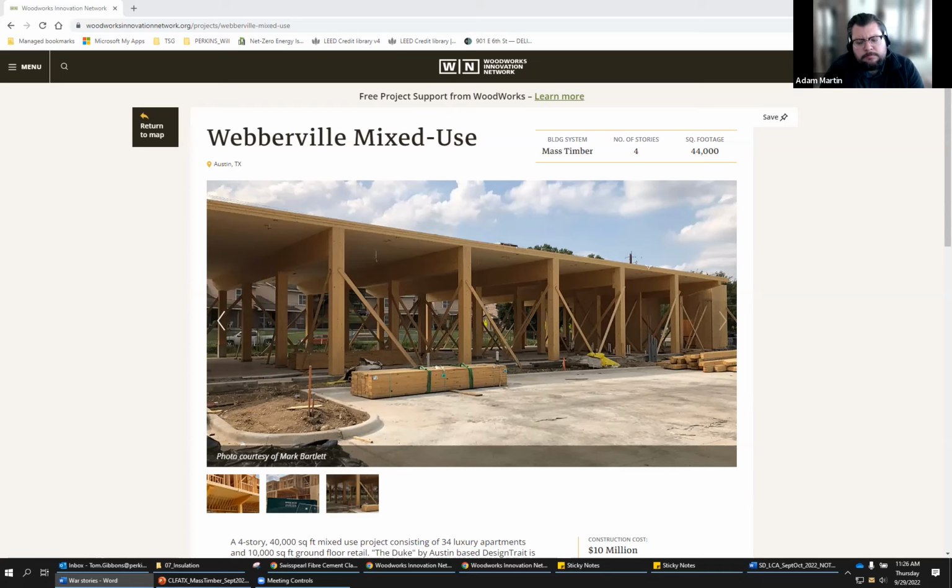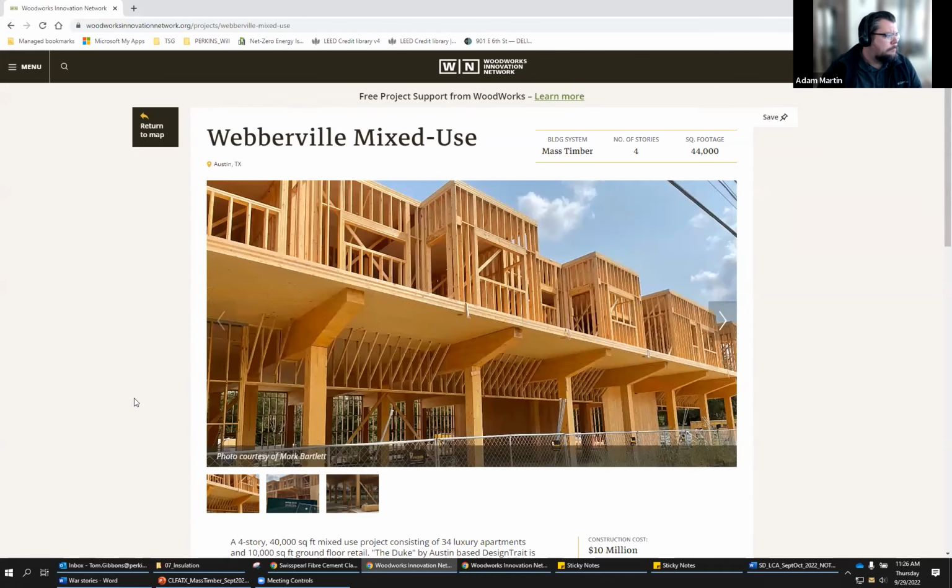So typically the assembly of a mass timber floor system has the mass timber itself, and then above that, some sort of acoustical material to provide a break for the impact transmission. Usually that's a half-inch to an inch thick material, depending on manufacturers. And then above that is going to be a topping slab, which also improves the acoustic characteristics, but also provides vibration resistance.